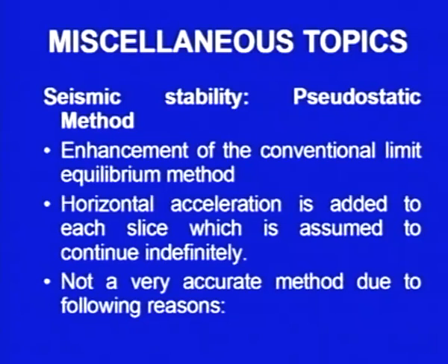So, friends, I have discussed various methods of slope stability analysis, and now I would like to devote a few minutes to some miscellaneous topics. The first topic which I am taking up is seismic stability. We took this case as one example, and the method which we are using here is called the pseudostatic method.